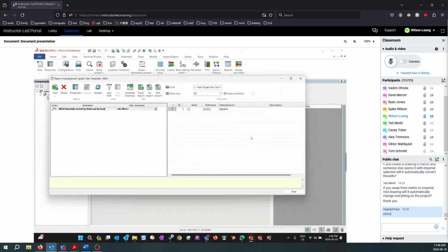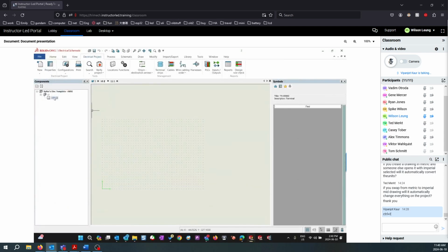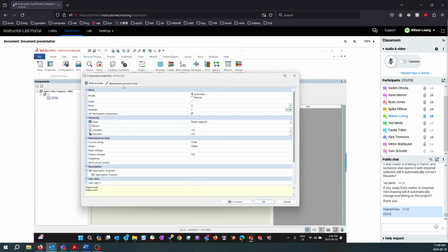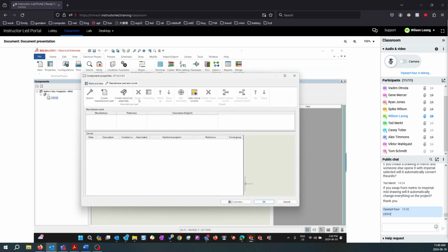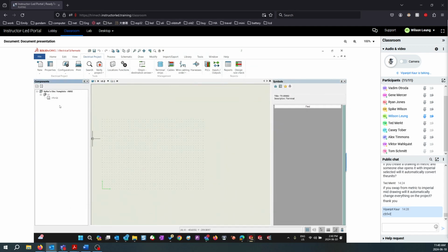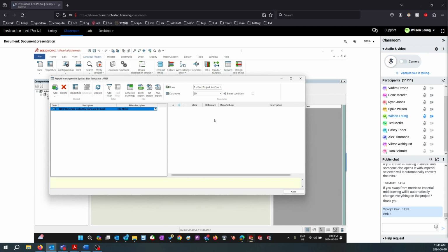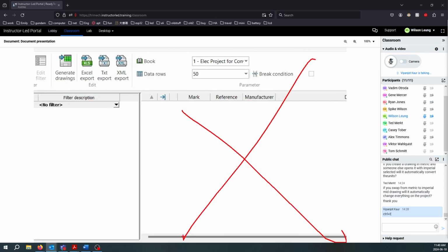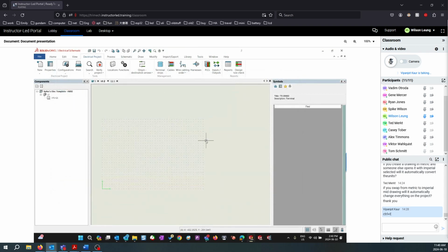component mark. And if I would go ahead and not link, if I go to the properties and do not link the manufacturer part number on this, if I remove that, if I say, I don't know, I know I'm using transformer, I don't know the part number yet, and if I'm sending a BOM list to Tom, and I added 20 parts, but none of the parts have manufacturer part real life number defined, in my reports tab, my report's going to be empty. It's going to say, Vip, you added components, but none of these components have manufacturer part data linked to them, so they won't show in your BOM.